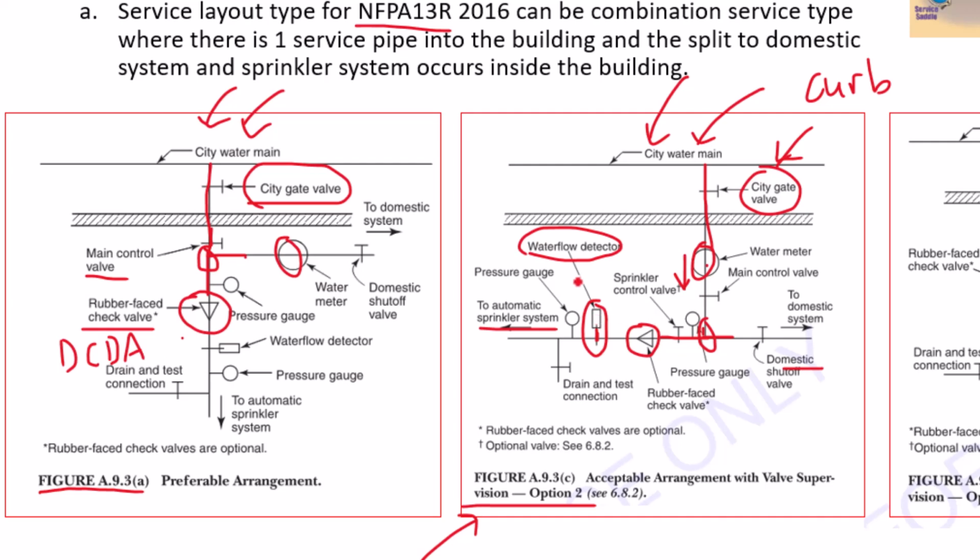If you don't have a fire alarm system, these water flow detectors can actually be wired to an exterior bell that will ring, and there'll be a sign next to the bell that tells people that once they hear the bell, the fire department can be notified.